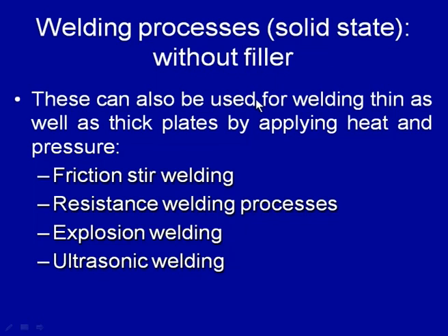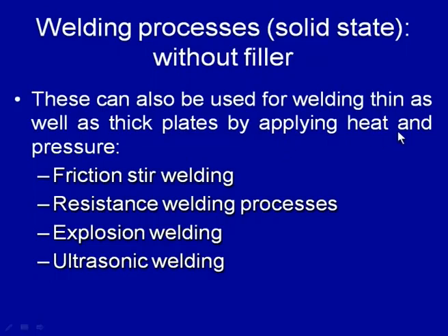In the previous sets, we have seen that fusion of the faying surfaces is done, but no filler material is used, and in these welding processes there are certain welding processes where filler material is not used, but the weld joint is performed in the solid state itself. And these can be used for thin as well as thick plates by applying heat and pressure, and various approaches are used for developing the weld joint in the solid state or in the semi solid